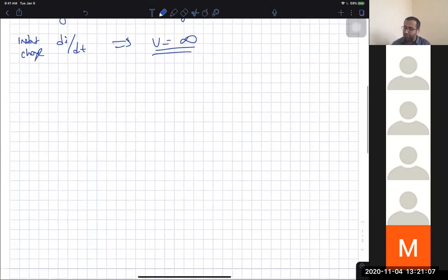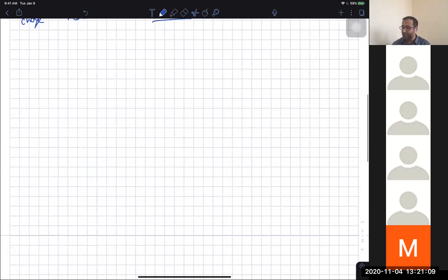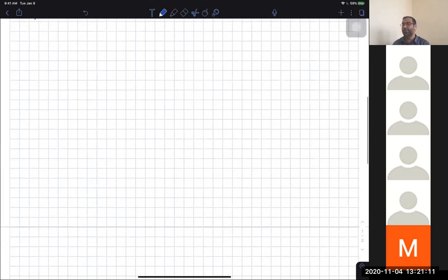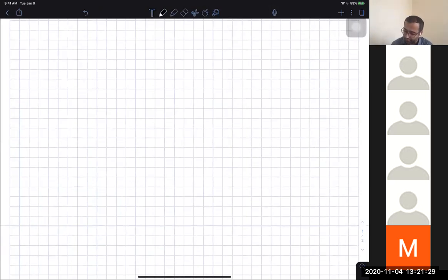Let's just work on a very simple example so that we can understand this current-voltage relationship. I will plot this graph of a current across the terminals of an inductor so that we can calculate the voltage drop across time given this curve. I'm trying to plot this axis as fast as I can.